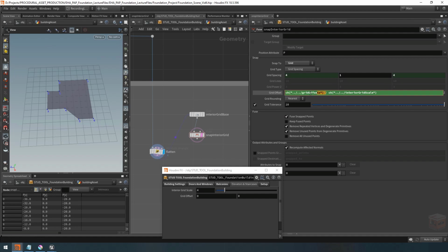Now, if you're doing this and you actually want to make sure that you're referencing a correct value, you can simply check while you're typing, and it will give you actual parameters that you can grab if they exist at this address. So in this case, I could simply click on grid offset Y, double click, and it will automatically set it up.